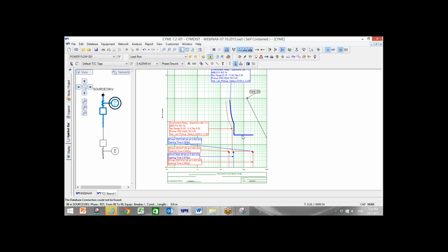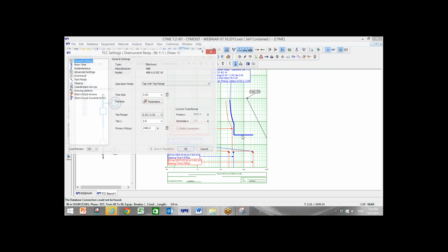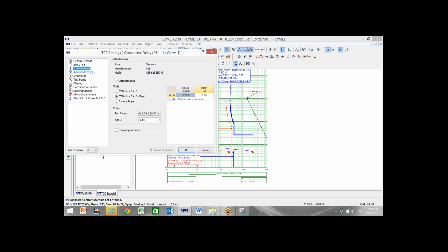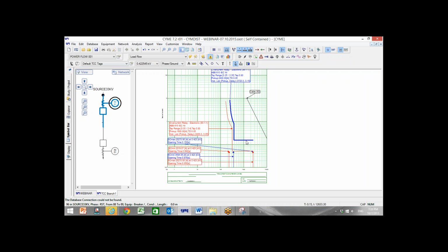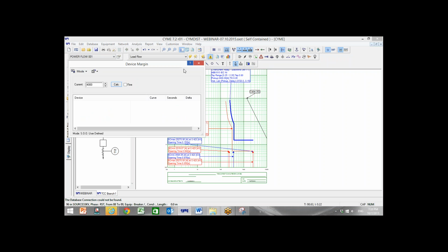So it's mandatory. Otherwise, for example, if I put it here, I have seen such things in many documents, believe me, they have this coordination. This coordination is wrong. It's totally wrong. If I go to this document and I calculate this, for example, 10, you can see the delta between these two is 0.1 second. This is not coordinated. This is the wrong coordination that nobody cares about. This is the problem that you should care about.